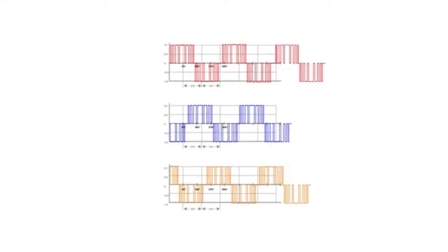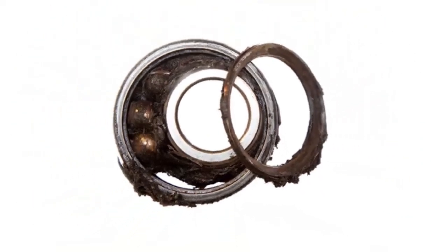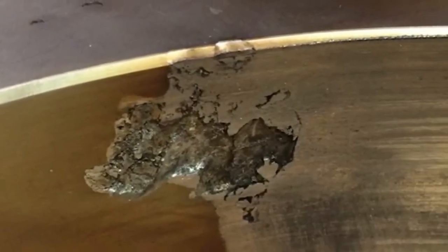Common mode voltage is created by VFDs switching IGBTs on-off continuously. This causes wear and tear on the motor bearings. The first sign of bearing damage is audible noise due to the bearing balls traveling over the pitted and frosted areas. How are these pitted and frosted areas created?